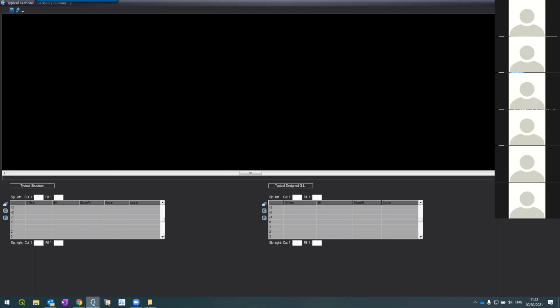So I'm clicking on the second segment and start defining its template. I'm starting at 0, 0.2. Very soon it will be easy to understand. I'm going 1.5 meters to the right with -2%. Let me start to the right, 1.5 meters.